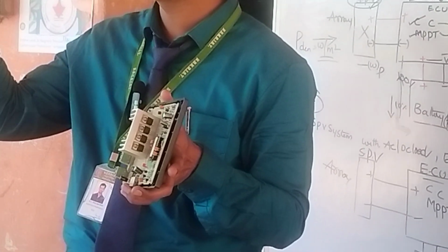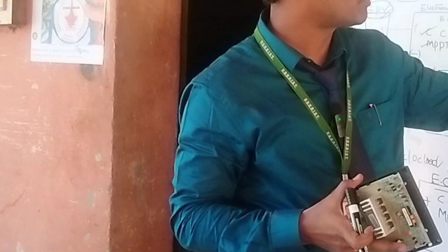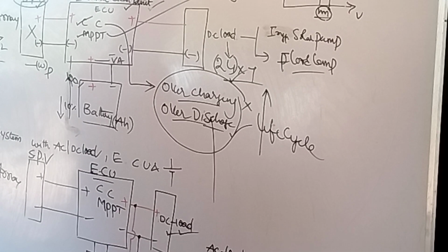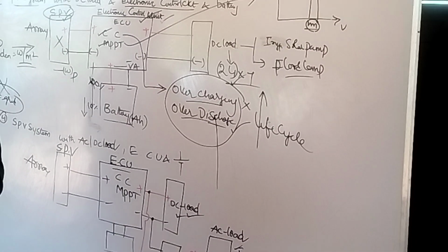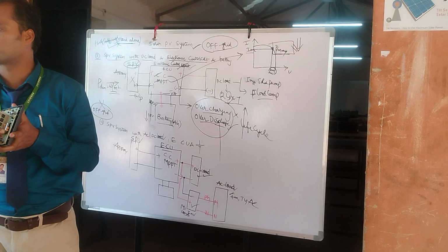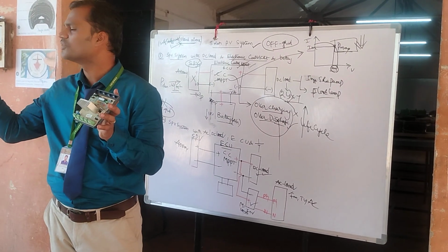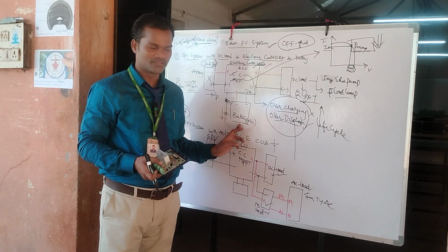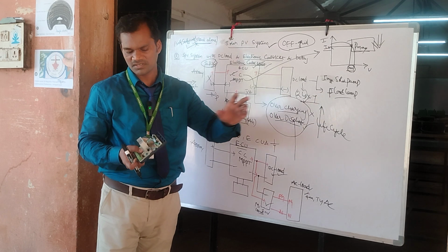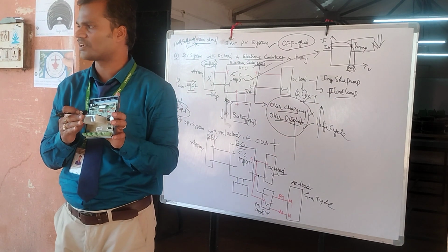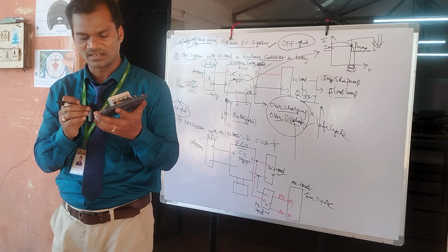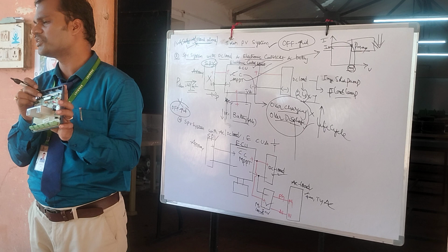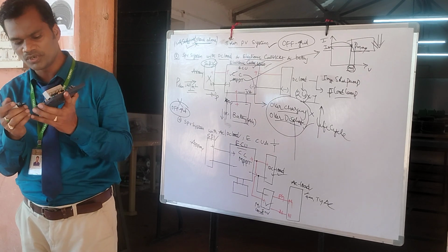So I am going to have an AC load with the help of a small inverter which is called a micro inverter. By using this micro inverter, the output will be phase and neutral. You can connect an AC fan, AC tubelight or AC appliances you have, water purifier, everything. Okay. So these sort of systems are which type of systems, sir? Solar PV systems which are called off-grid types. Off-grid means there is no grid in that location. There is no availability of electrification in that location. Then you can use this configuration and you can supply power to those people. So now this is about the off-grid system. Now we will discuss the on-grid system. How many on-grid classifications are there? And we will try to perform an experiment on the off-grid system and on-grid system.